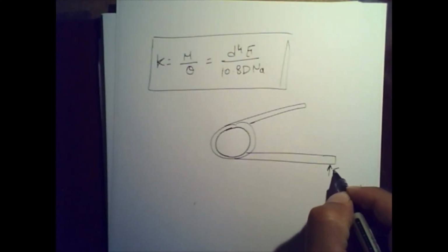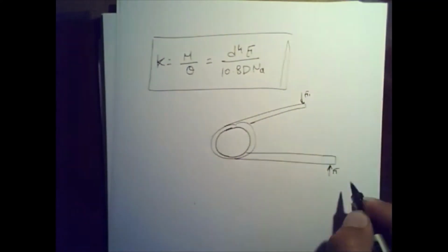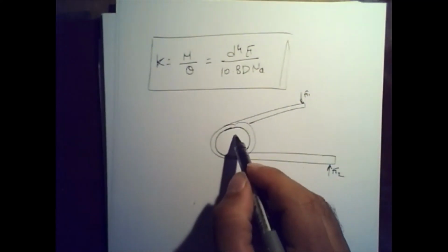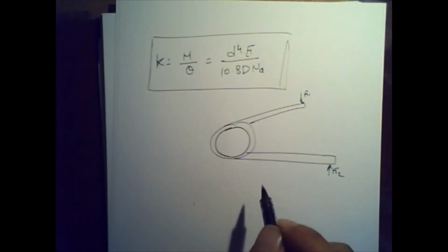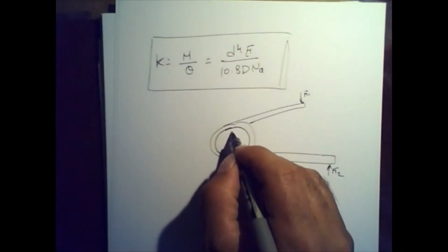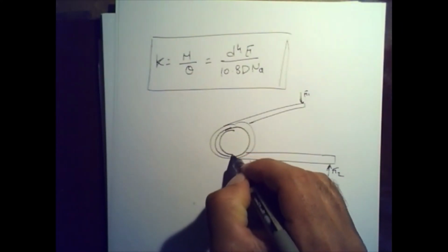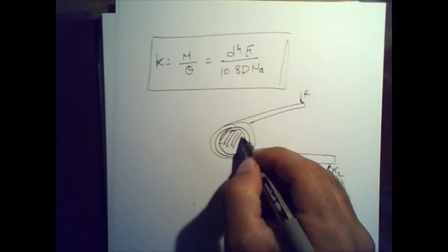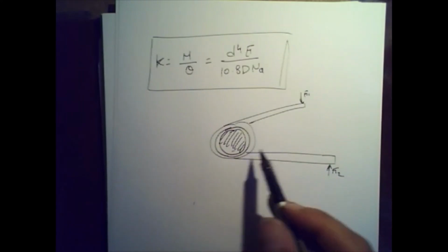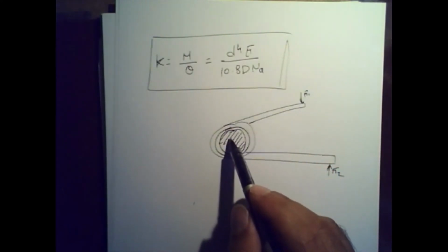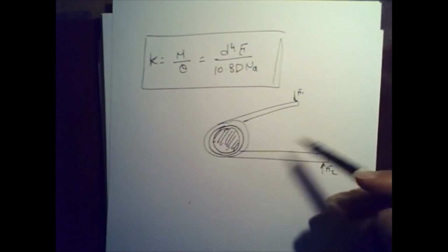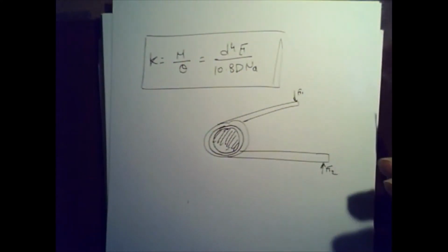As a result of applying these forces, F1 and F2, I'm going to essentially shrink the inner diameter of the torsion spring. Usually every torsion spring will basically have a pin on the inside. And this pin is used to be able to utilize that torsion spring effectively. You have to have a pin, right? And then the pin will prevent this guy from going up or down, right?